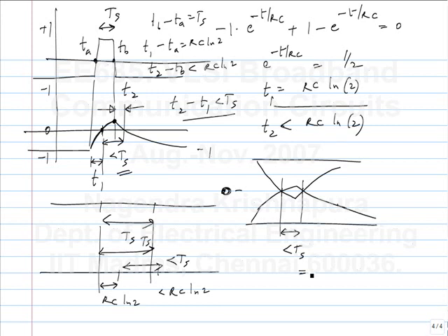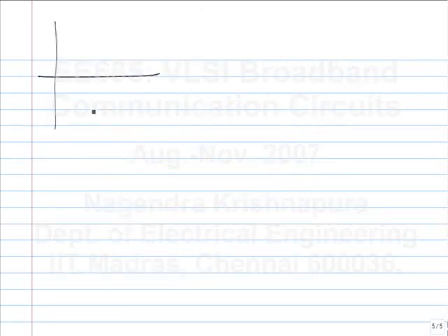horizontal eye opening is important for errors from jitter and vertical eye opening for errors from noise. Oh, okay. So we can discuss that if you want. So I was going to discuss equalization, but yeah, what was the eye diagram is still the same thing. You take some integer number of symbol intervals and then plot it. So let's say the input is a 4-level signal, maybe -3 halves, -half, half, 3 halves. I think I should make an animation with MATLAB or something and show it. That will become much clearer.